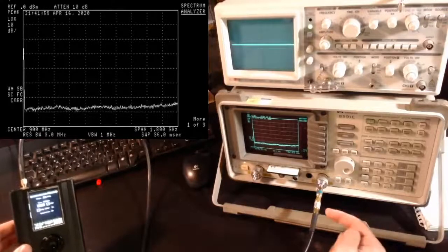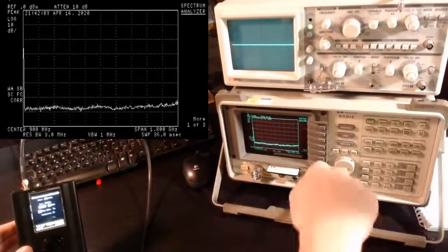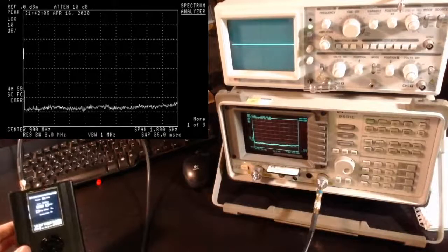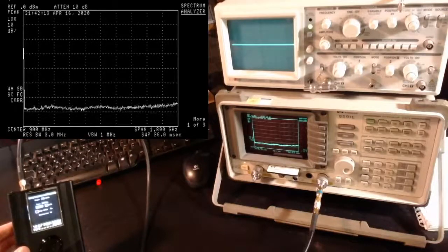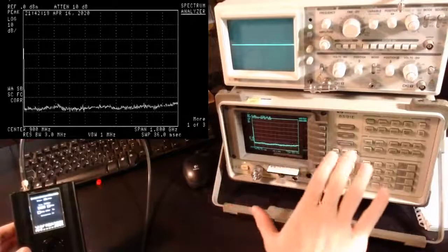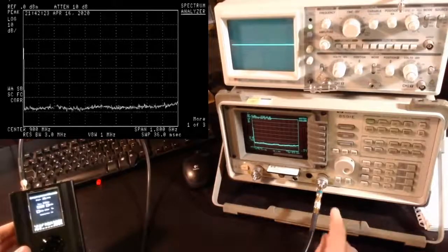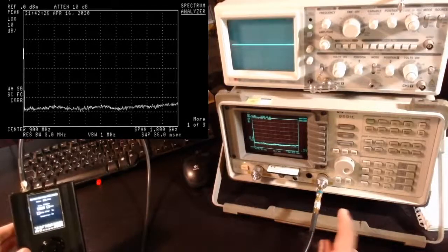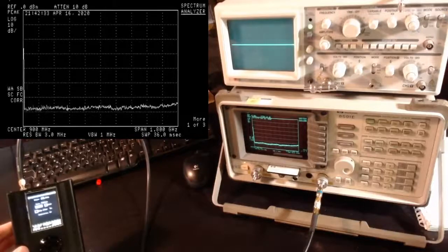I've connected the HackRF to the spectrum analyzer through a minus 10 dB attenuator and most importantly a DC blocker. I discovered that the Portapack extension always pushes 1.5 volts DC in its output. This spectrum analyzer can handle 25 volts DC, so it should not be a problem. But with other devices you might risk frying the input of the front end of your spectrum analyzer or your device. So just be careful.